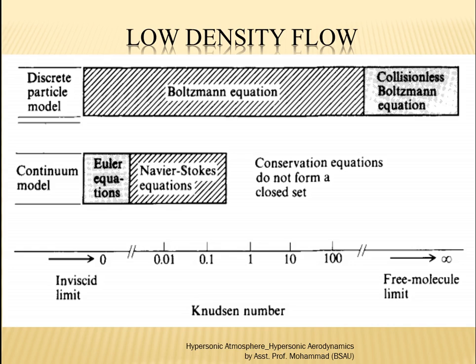condition correction. Beyond this altitude of 150 km, density of the atmosphere becomes so low that a need for change in governing equation arises in this regime. Hence, kinetic theory of gases finds its application for hypersonic flight at such altitude. In fact, a discrete particle model, which utilizes the kinetic theory of gases, is applicable everywhere. Unfortunately, it will be difficult to track a single particle in the continuum range, when the fluid is taken as continuum, because millions of particles are available.